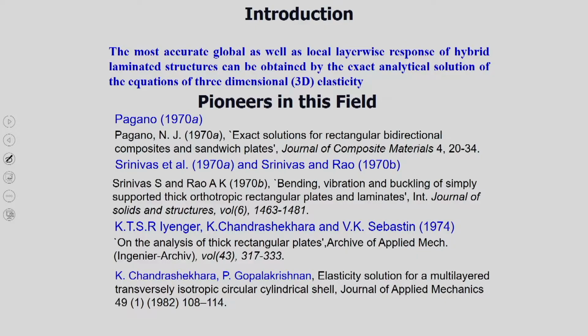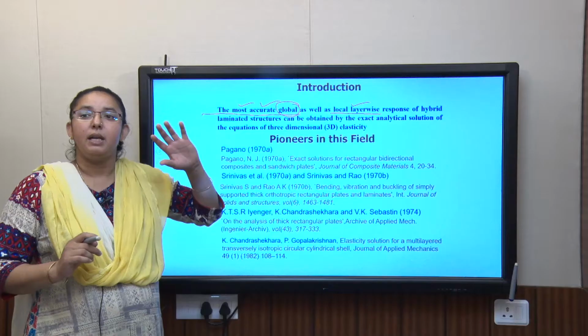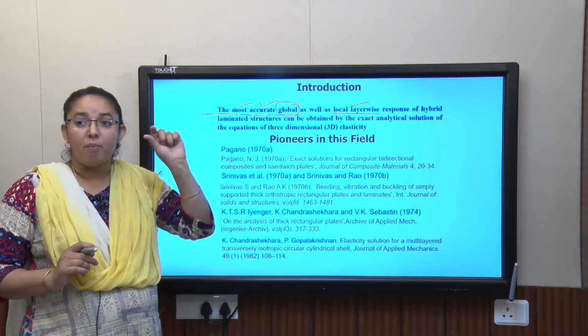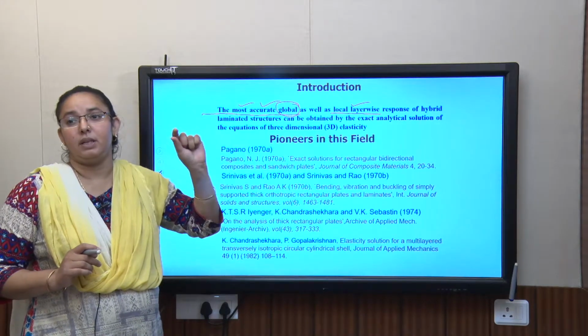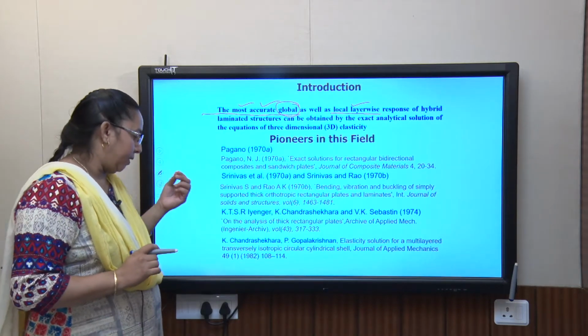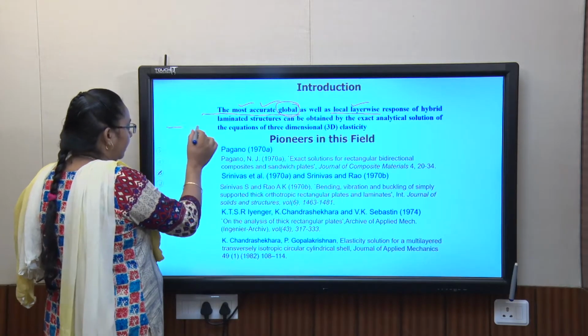Further, the three-dimensional solutions provide the most accurate global as well as local layer-wise response. If you talk about two-dimensional theories, if you consider only equivalent single layer theories, they can give you the global response accurately, but the layer-wise response they cannot predict accurately. A very famous example, let us say